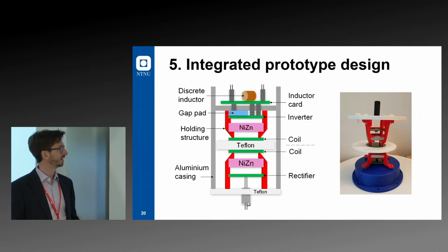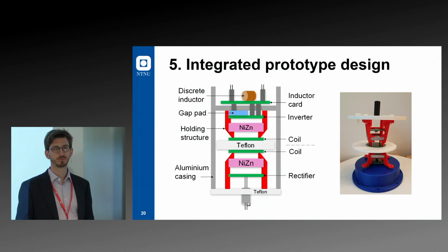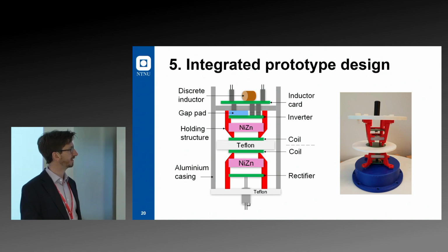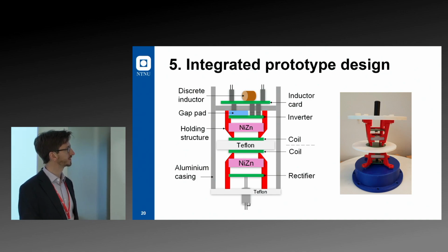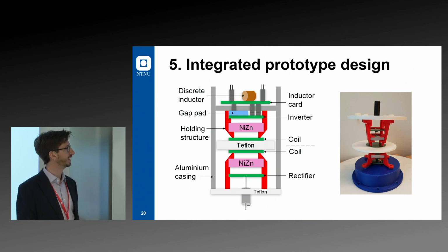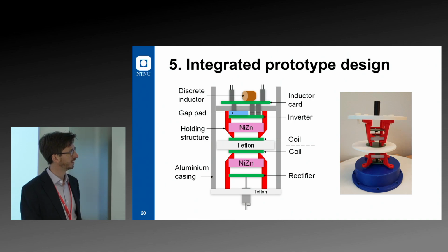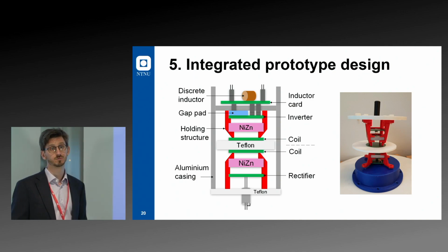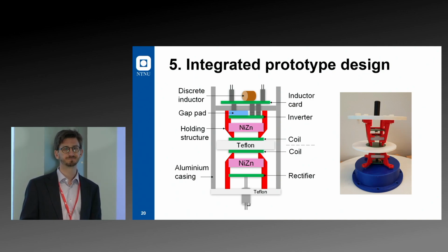And then we make a stack up using printed parts to hold it all in place. So we have the Teflon, the coils, we introduce some magnetic material for shielding the electronics, and then we have the inverter and rectifier on either side. And you can see the current mock-up. Due to COVID and sourcing issues, this work is not finished yet.